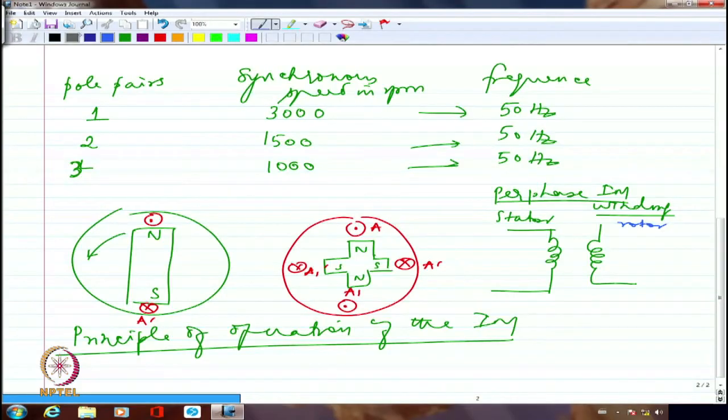Okay? Now, I told you that it has to be short circuited, so I am short circuiting it simply. I have applied 3-phase currents to all the 3 phases of this induction motor's stator winding. So I have just connected a voltage source and applied the current. So the current drawn should actually be enormously high.